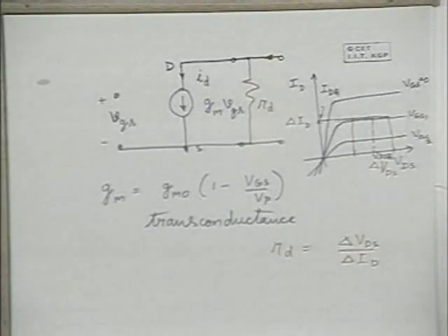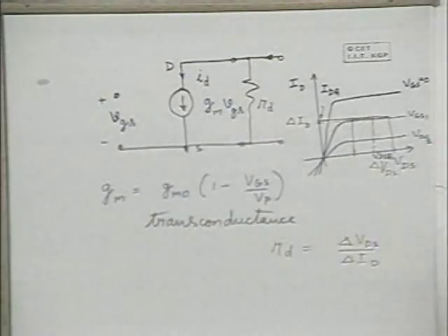So if we want to show the effect of high input impedance, here we are assuming infinity. How will we show that? In the small signal analysis, if we want to show the high input impedance, it is by an open circuit. If it is infinity, it's an open circuit.